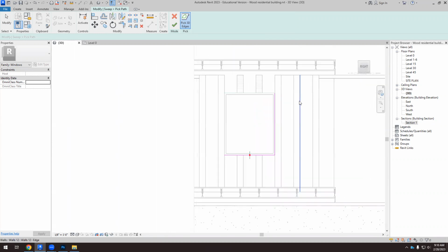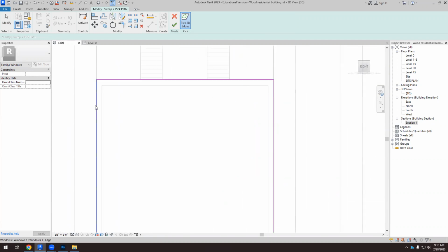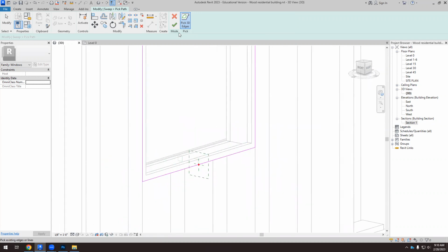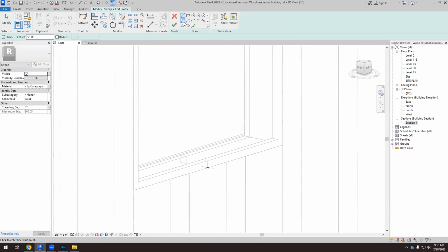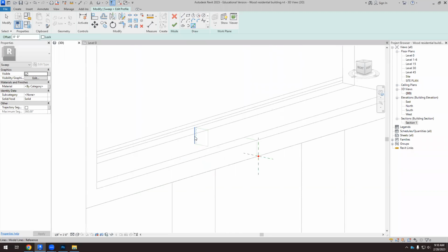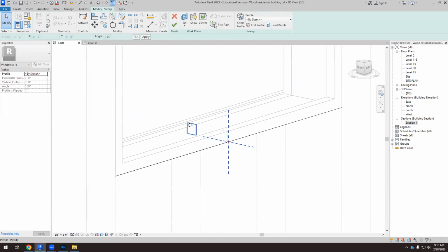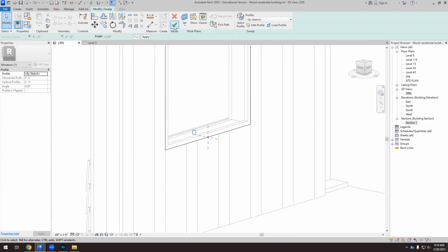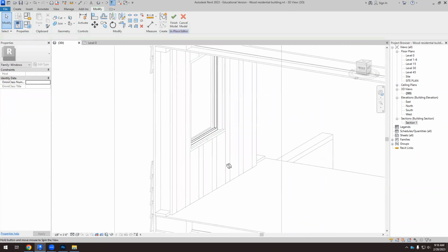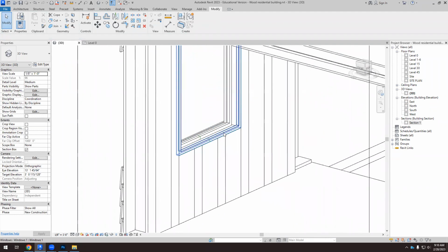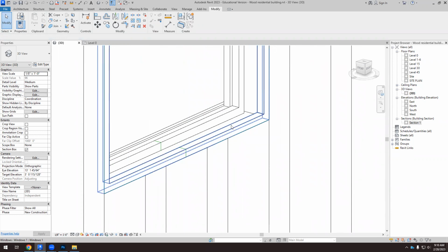Now, if I continue picking 3D edges, then I can pick this one, and this one. And this one. Okay, so that was easier. And now I have to select profile. I edit the profile. I pick lines here. So this is 1, 2, 3, and 4. I click OK. And I hope it will work. Yes. And finish the model. Okay, the second one was easier.